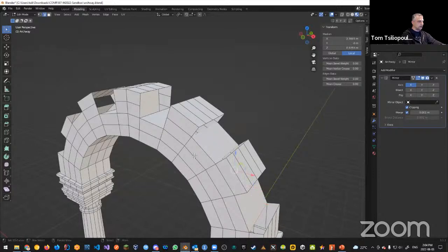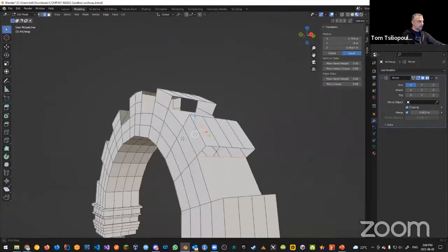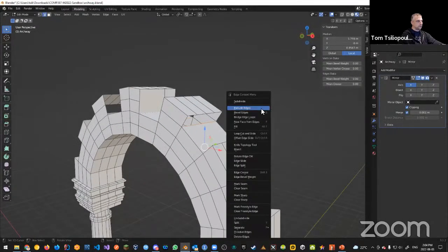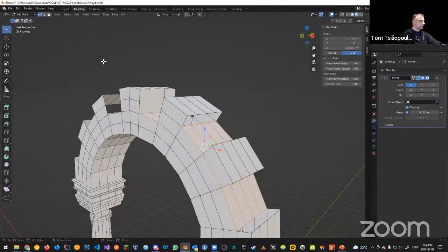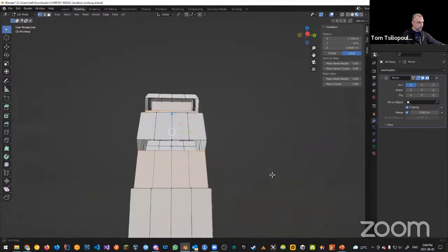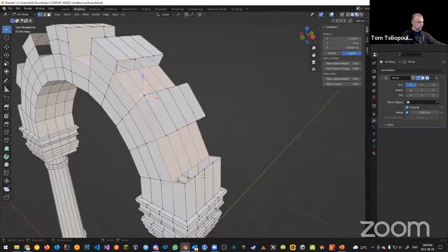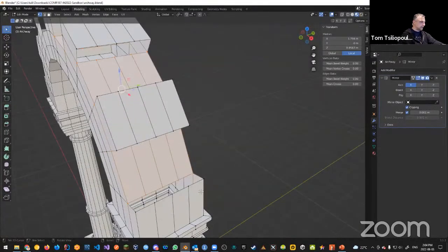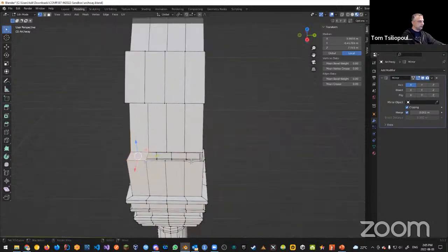I'm going to go to the reference as much as possible and select all of these edges right away, all at the same time. And then I'm just going to subdivide them and make them 3 subdivisions, just like we did before. And then go to vertex select mode, and you can see that now we have the geometry needed here, right? And we're just going to connect these faces here as well. So again, we'll start with these faces. So this one, this one, this one, and this one, and then connect. And it's a bit tedious, but it is what it is.